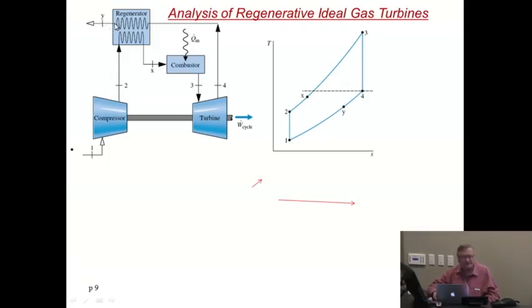So in reality, if we are going to make a cycle, the cycle is going to go from 1 to 2, 2 to x, x to 3, 3 to 4, and then 4 to y. So this is the heat out. It's hy minus h1. And y is necessarily below x, because you have dumped the air in here. It might be below 2, but not necessarily so.